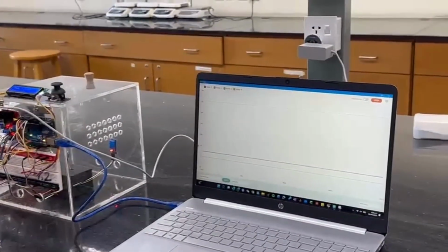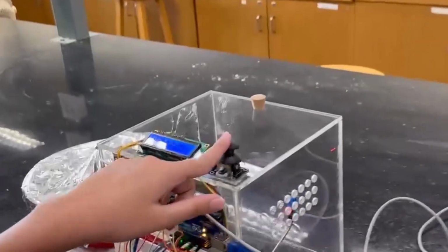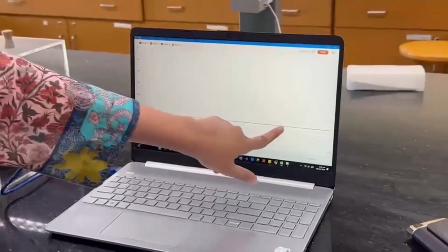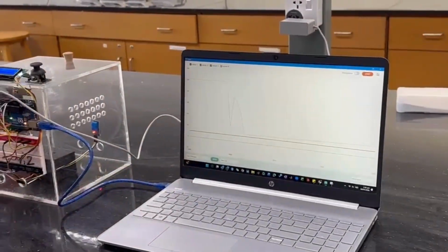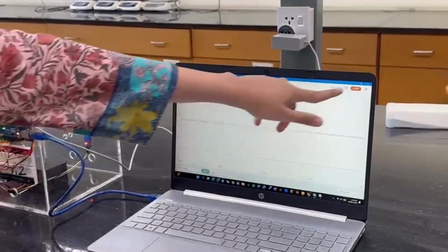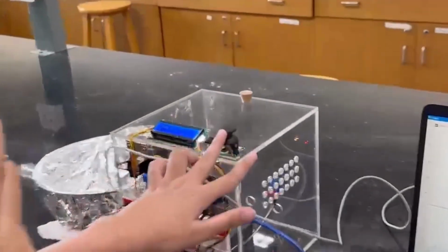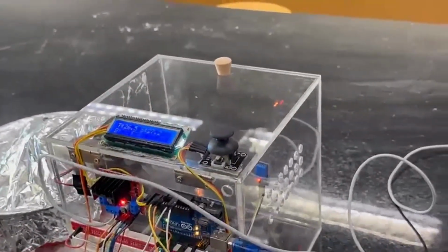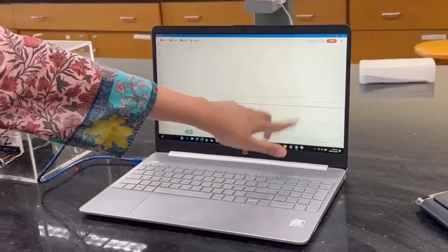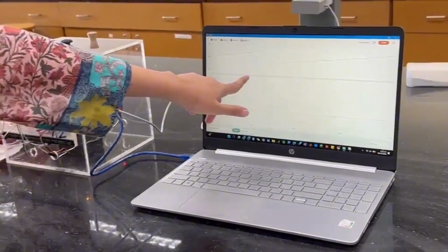If I were to change this, you can see if I increase the temperature, then the fan's power output goes down, and still going down, down, down. This is the fan, it's fluctuating according to what we need. And if I increase it a little more, because I want heating, look, the fan power went completely to zero while the bulb power rises and fluctuates according to what your actual control output is doing right now. So you can see the temperature is also rising over here.